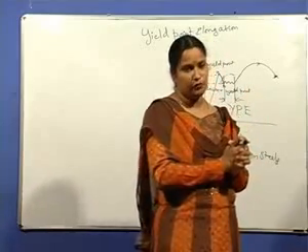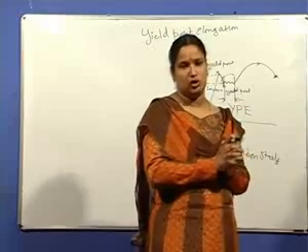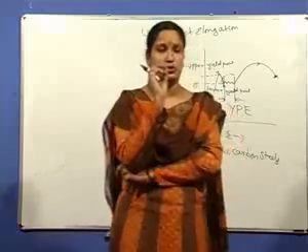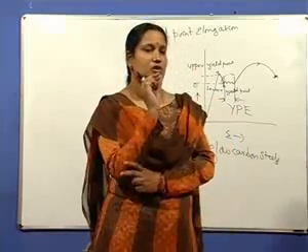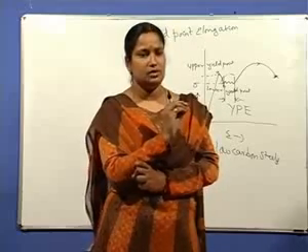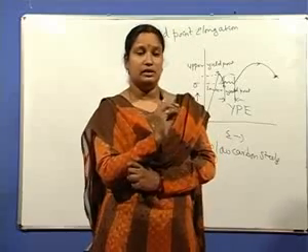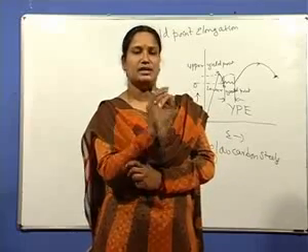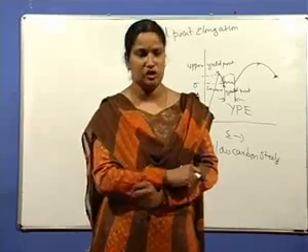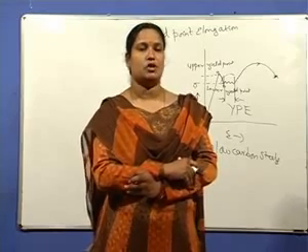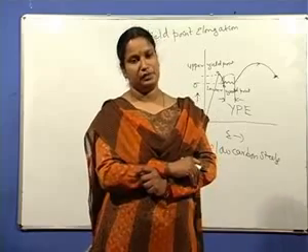For interstitial solid solutions, where the solute atoms are very much smaller than the solvent atoms, they occupy positions exactly below the edge dislocations and form atmospheres known as Cottrell atmospheres.